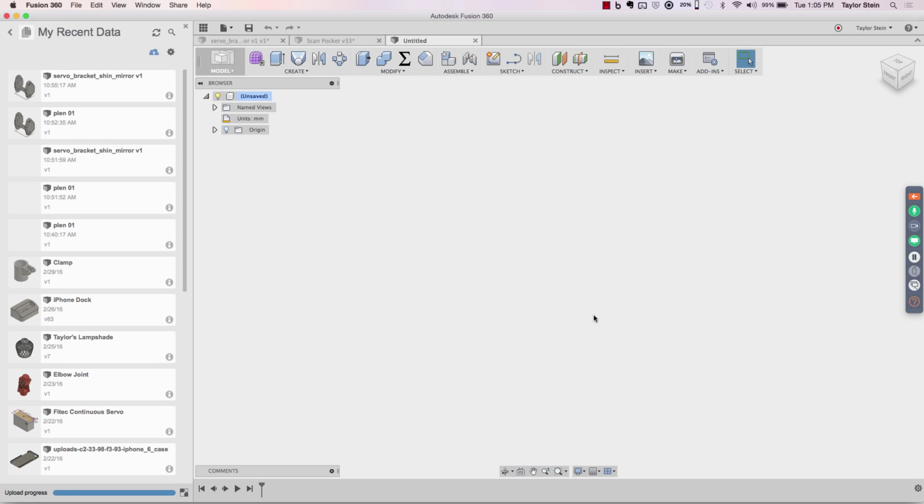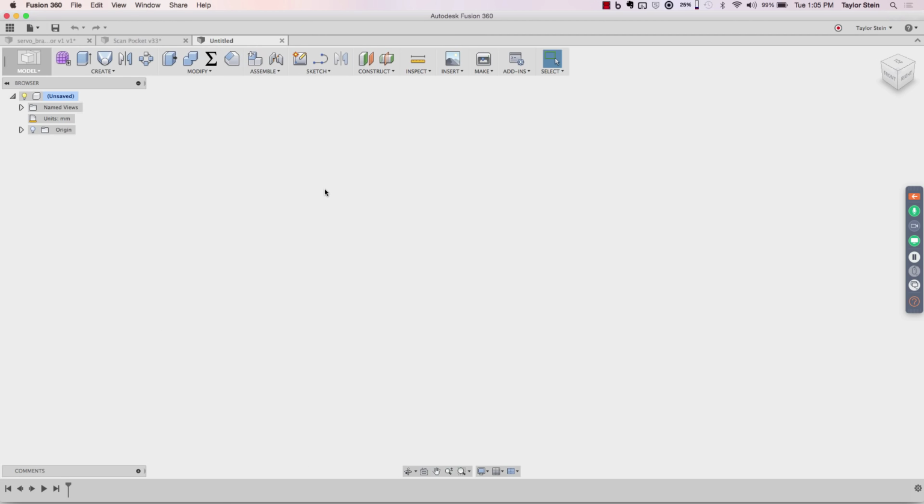So once you've selected a file to upload, it'll go ahead and upload it to Fusion 360 and translate it for you, and once it's done translating, it'll appear right here on the left-hand side in your data panel. So that's really all there is to uploading files to Fusion 360, and the first example I want to cover as far as neutral file types is how we work with files such as STEP. So STEP is a neutral CAD file type that really is a solid piece of geometry that you'll be working